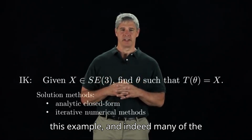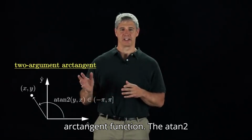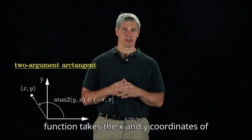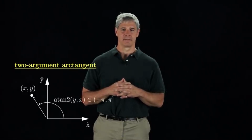For this example, and indeed many of the inverse kinematics problems in robotics, it is useful to define the two-argument arctangent function. The atan2 function takes the x and y coordinates of a point in the plane and returns the angle of a vector from the origin to the point relative to the x-axis.